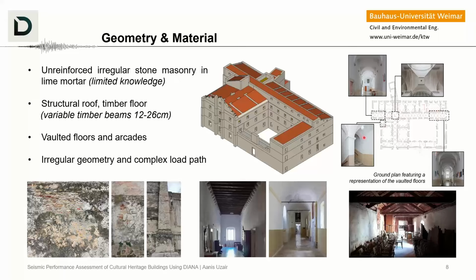For example, we have very complex vaulted structures where we have cross walls, sometimes barrel walls, and sometimes different cross walls coming into the corridor, connected in different directions in a very complex way, like this, for example. The material is very diverse, which means that bringing this into a continuum brings a lot of uncertainties, and we must not work with one material set.